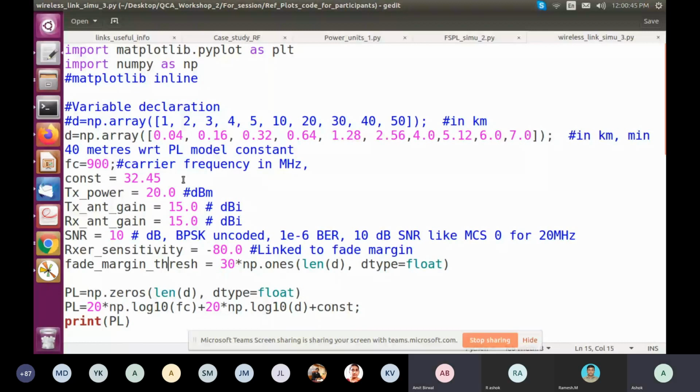Yes, I can see. So you can change this variable depending on what you think is your particular wireless system that you're designing, and then with that degree of reliability, you can go ahead and design. See, this is left as an option to the wireless designer. I am claiming that with an 8 dB fading margin, the link is only 90% available. That means it is not available for 10% of the time. If you're okay with that, you can go ahead and design. This is a parameter given to the wireless designer to come up with his own design.